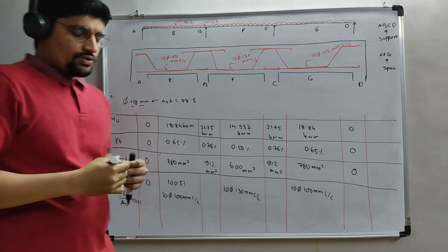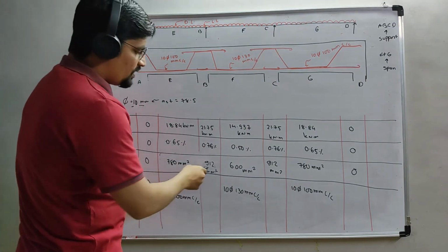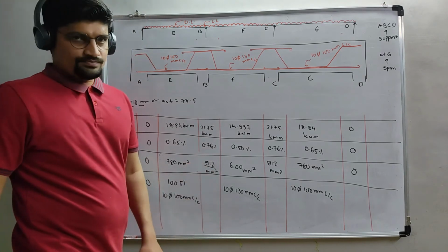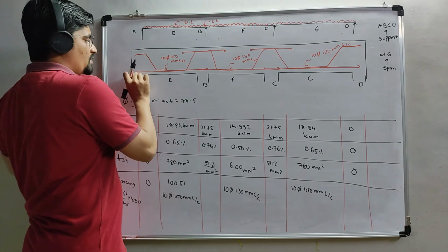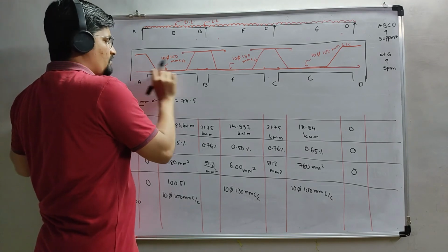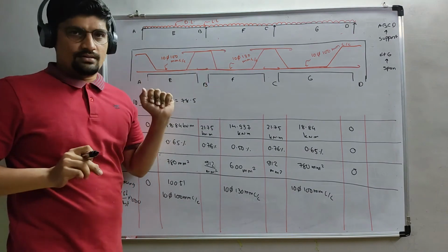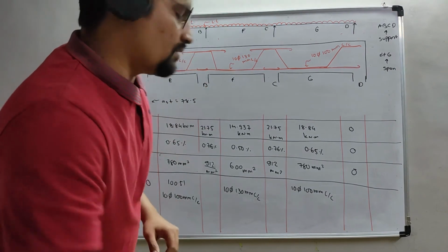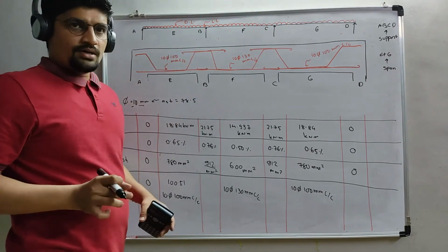Okay. So I want to explain to you that here we need 912 mm square AST, but we see here that this bar starts from here and the half bar is ending here. So the half reinforcement of 780 is on the hogging portion.